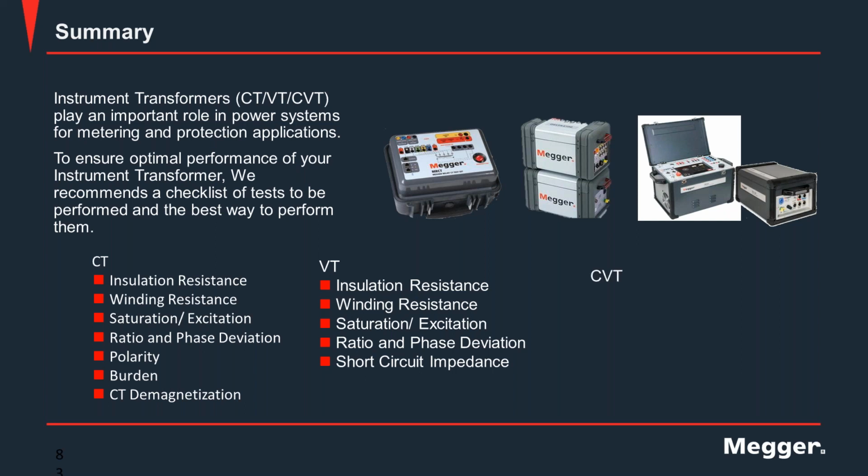And for the CVT, we have the insulation power factor or tan delta testing. We have the capacitance testing, which is the testing of the stacks of the CVT. And we have the ratio and phase angle deviation test for the CVTs.